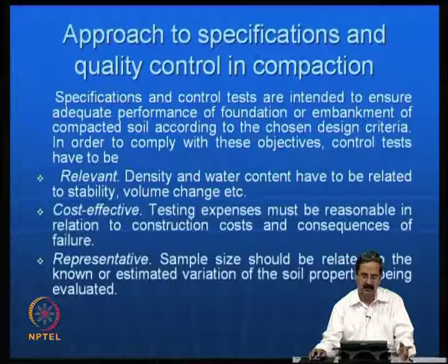So, this density and water content have to be related to stability. For example, the shear strength of the soil at that particular density and water content, or in a particular range of water contents and density, is what we test.